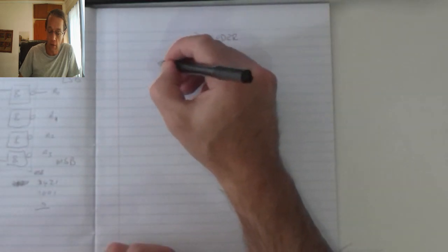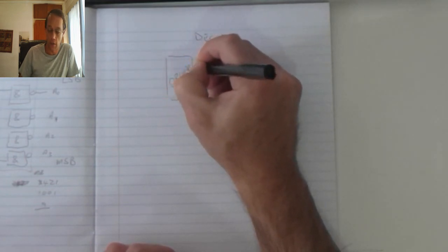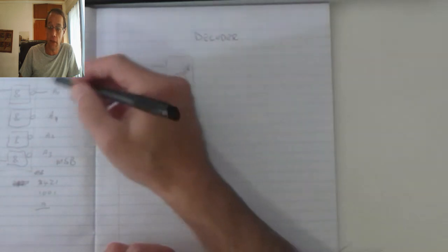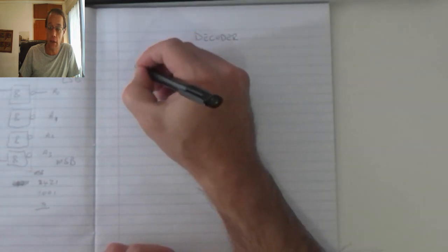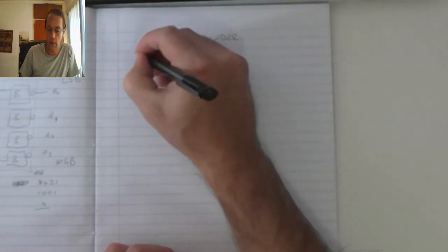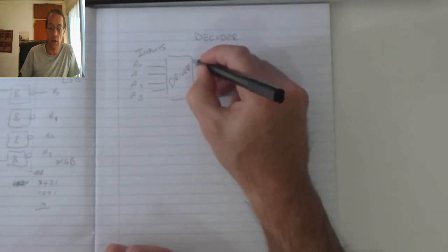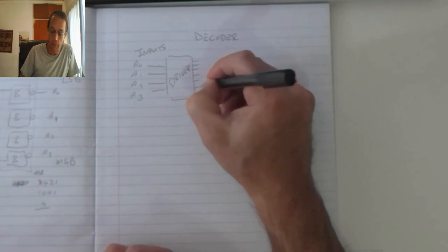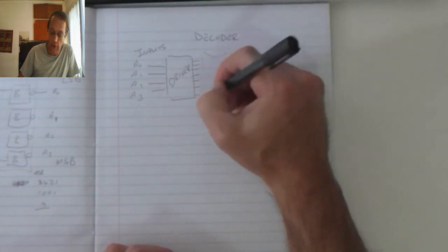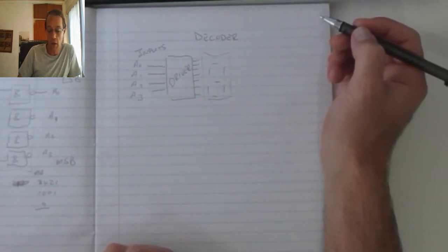It has to take information, which we got here from my encoder, A0, A1, A2 and A3, which are my inputs, and it needs to convert that into 7 outputs, which we will then use to connect to my 7-segment display unit.